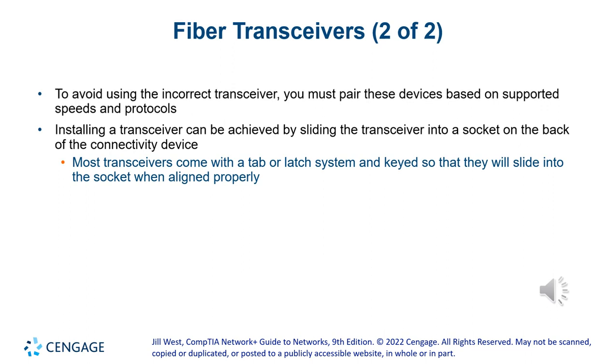So the wavelength, if you go into higher wavelengths on the light spectrum, you will see 850 nanometers. That's the one used for multi-mode fiber, or 1310 nanometers. That's used for single mode fiber. If you don't know whether a transceiver is for single mode or multi-mode, you can look at the transceiver itself, and you'll see that it says 850 or